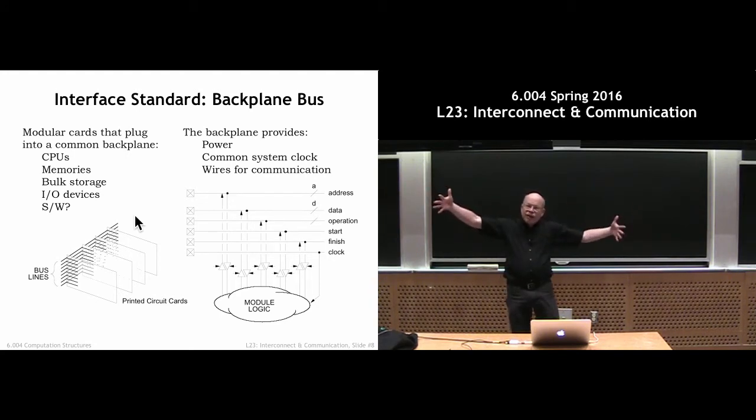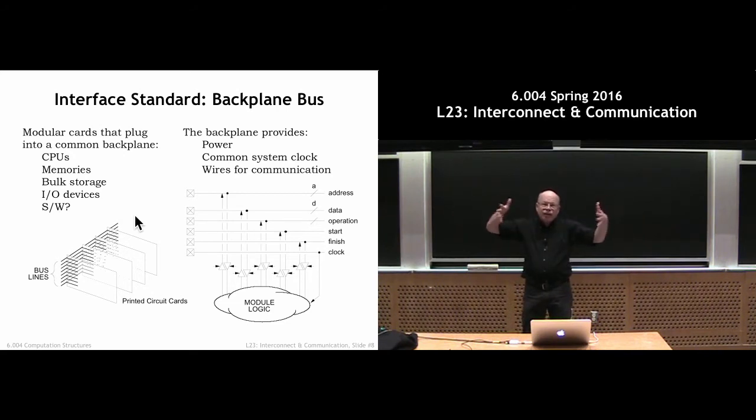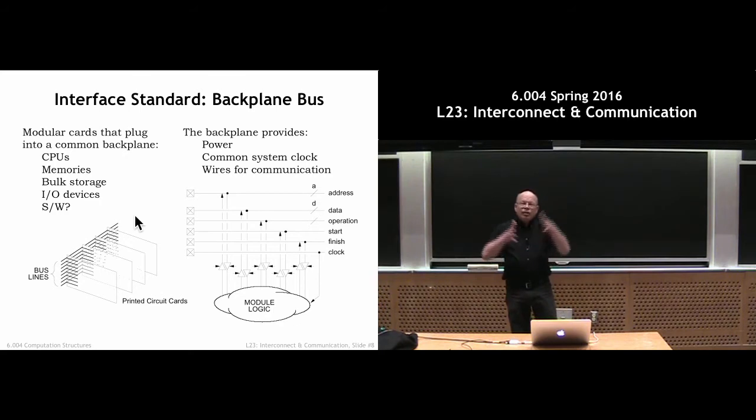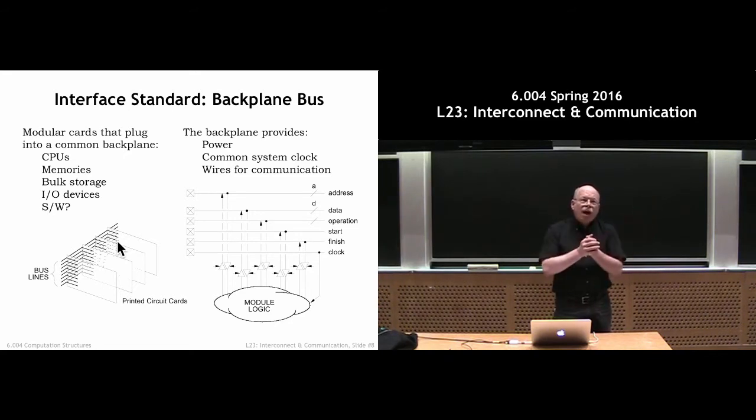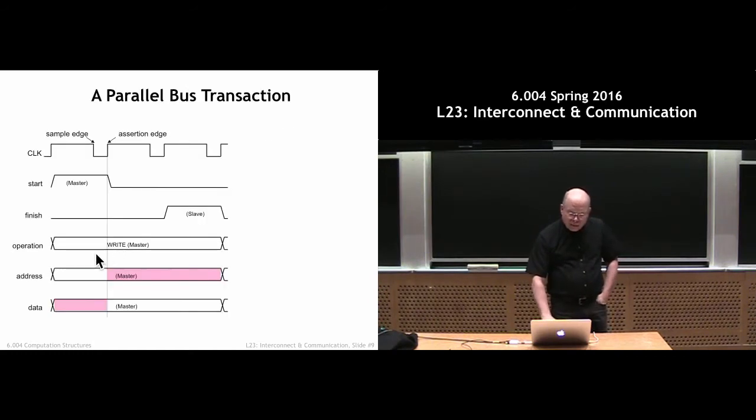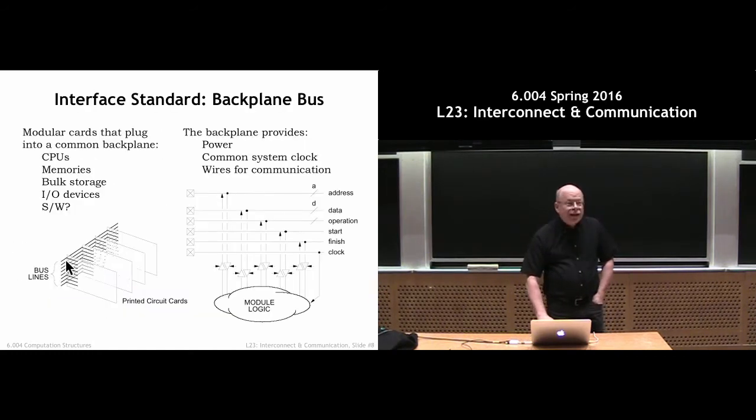So you have 100 nanoseconds to get a 32-bit word from one place to another, which was long compared to the distances involved. And so we built these backplane buses, which were just long pieces of copper wire with connectors on them. The connectors let you plug in boards that could make electrical connections between signals on the boards and signals on the backplane. That was a pretty neat technology and worked really well for the first 50 years of electronics.